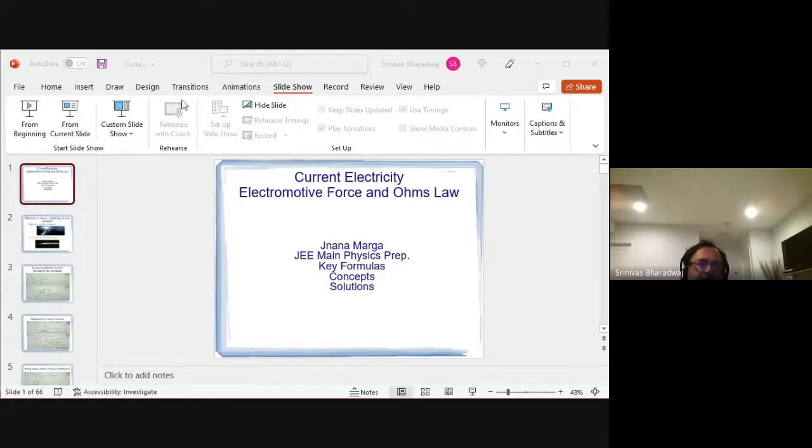Otherwise, you can just go three loops, this loop, and this loop. Three loops and three voltage equations, and internally you reduce the unknowns using the junction rule. You need only three unknowns here in terms of the currents. Okay, so that's the critical thing. So here you have only one loop, so introduce only one current, and therefore that current is I, and all the elements in series will carry the same I. Keep that in mind, and then you solve these current problems.